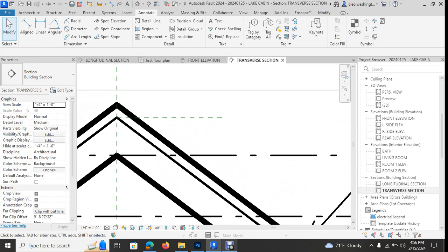Typically, when you're dealing with wood, okay, if it's a 2x6, that's the nominal size. The actual size is going to be 1.5 by 5.5, and I will give you guys some wood size charts when we actually start the next model. Didn't want to roll that out right now. Didn't want to confuse you.